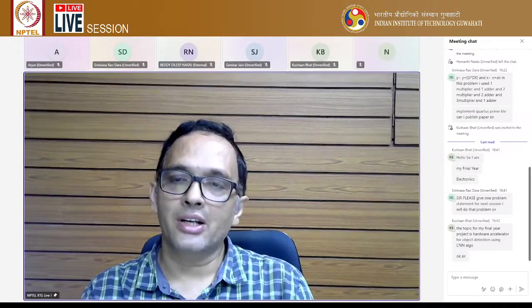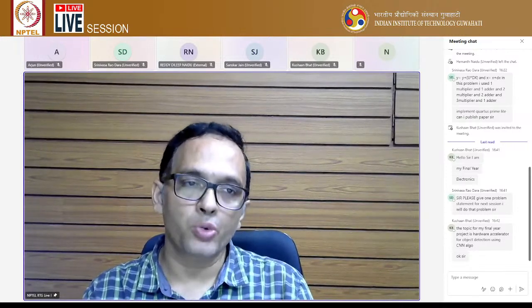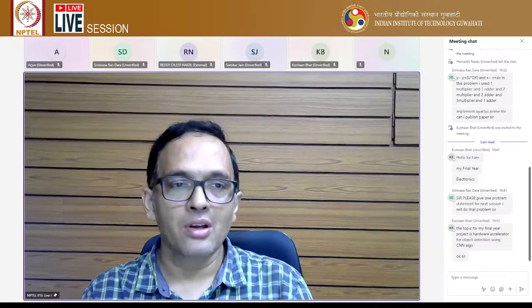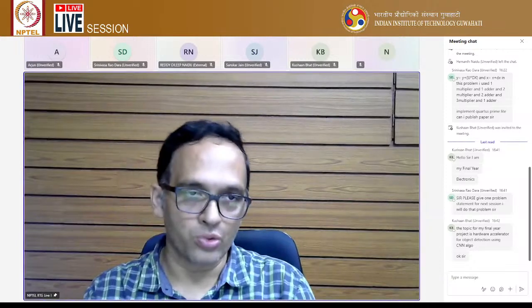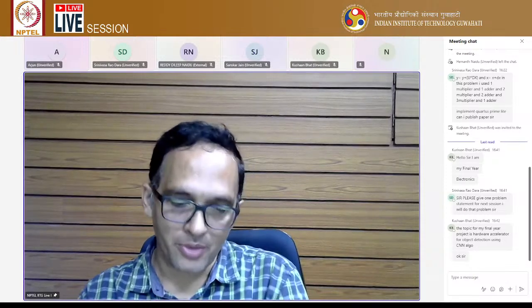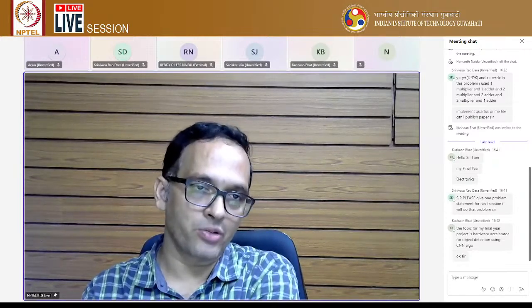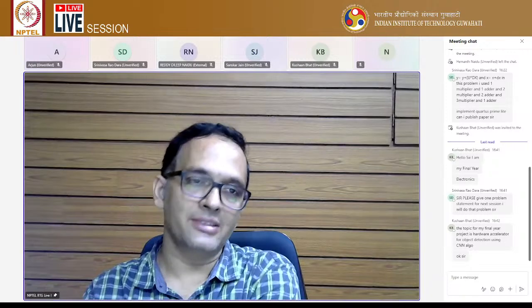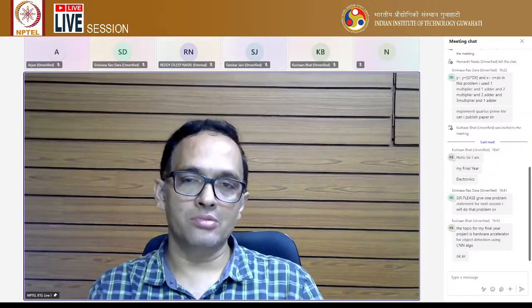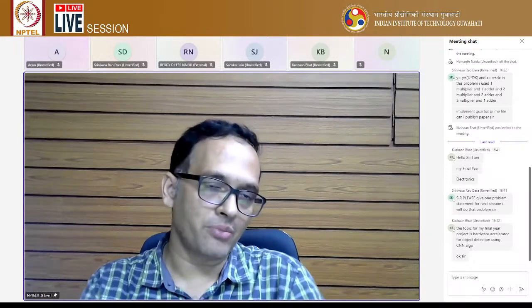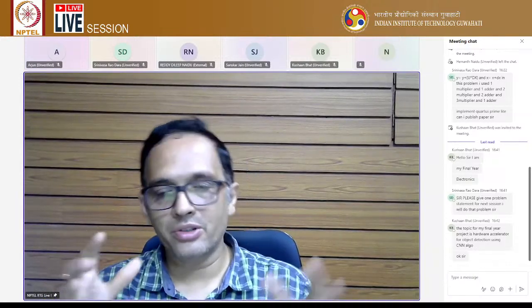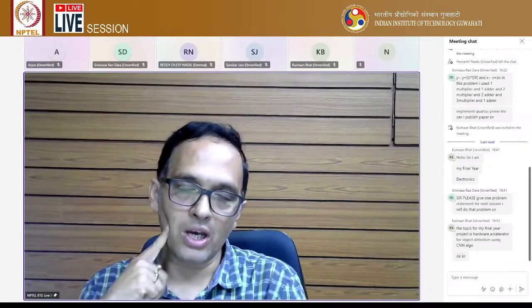So I asked them to generate the basic hardware version, which took 2 weeks because a lot of things were not synthesizable and they were not familiar with the tool. So that takes some time. And then they try to optimize the design. Then we defined a problem statement: given an area constraint, that means your FPGA board is given to you, so you know what your area is. Say you do the basic synthesis and the design is taking too much area, right? It's not fitting into the FPGA board. Then what kind of optimization is useful so that you can reduce the area and your design fits into the FPGA board that you have?